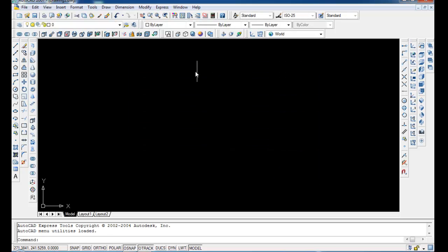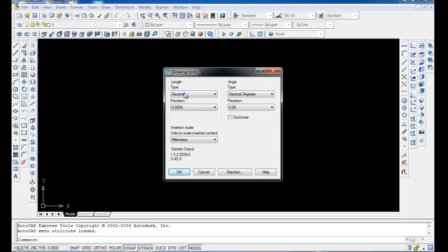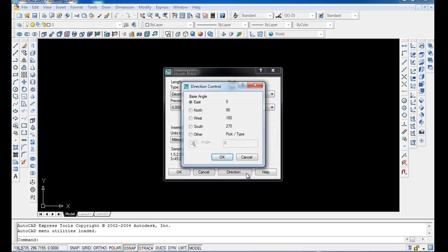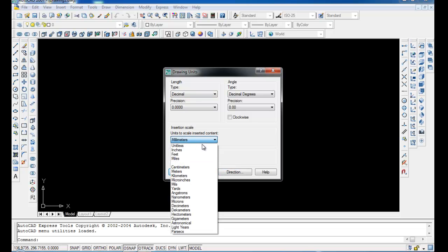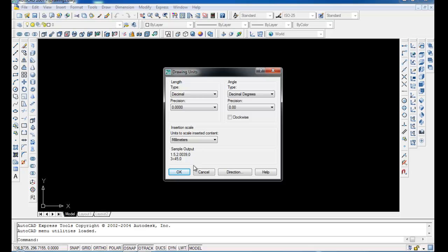When you finish it, you are going to get the AutoCAD workbench. The cursor is just considered as a mini drafter. According to your requirement, you can use it. Then you can directly go ahead with Format, then go for Units. When we go to Units, you get the same dialog box: decimal, degrees, counterclockwise direction of measurement, as well as the insertion scale factor. In that you can select millimeter. Select it and just make it okay.